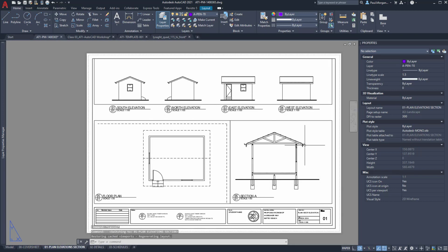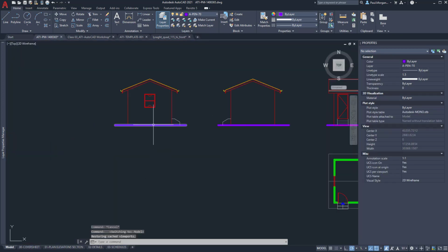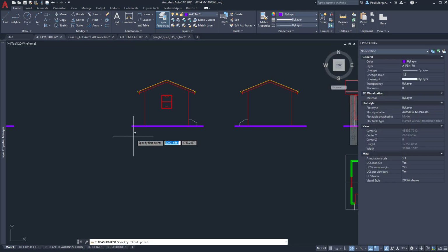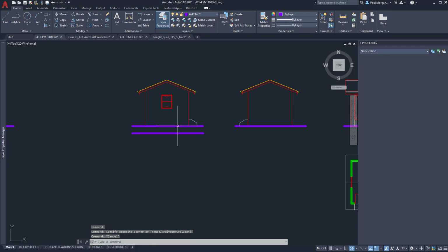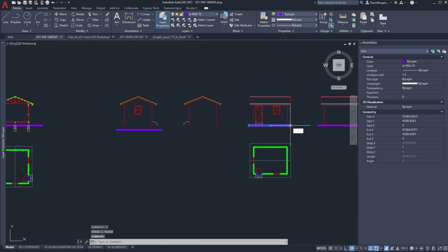We do have more to add here. The other thing to look at is the length of the ground floor, making sure that that's even. These are very little things that aren't really going to change the material impact of your drawing, but it does change the legibility of your drawing. So I'm just going to double check. What is the distance of that ground line? Yes, some random number. So I'm going to just hover over, draw across, and I might draw across, say, 6 meters. And I'm going to get rid of this line and that line and all of these as well.